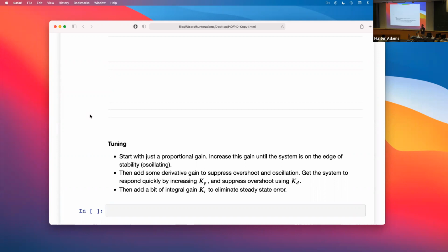Even in lab 1, you had pretty substantial time constraints for the computations you were doing. In this one, we're interrupting at 1 kilohertz, which means you have 44,000 cycles to spend. That's plenty. You could probably get away with floating point. Don't, but you probably have time to get away with floating point if you wanted to. So the performance will come more, once you have the controller implemented, you'll get better performance by better tuning those gain parameters.